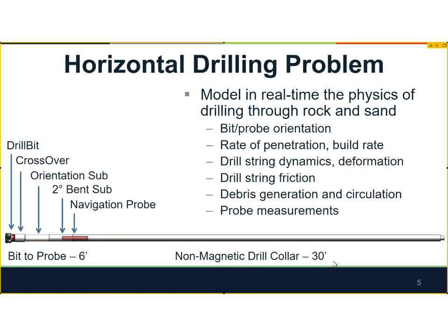And so we're modeling and capturing the deformation of the drill pipe and the bending and twisting of that drill pipe. When you turn the drill at the rig, you can have as much as a degree of twist in your drill pipe for every 1,000 feet. And so it may take a while for the actual bit to respond. That's why we're measuring the orientation of the bit right here, so that they can know that even though you may be turning the rig up hole, your pipe down hole may not be turning at all.